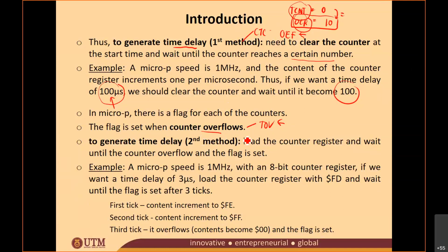Okay, the second is the overflow method. In this overflow method, you load the counter register and wait until the counter overflows and the flag is set.